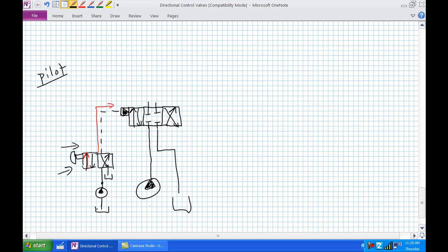Super pump is over here. Baby pump is right here. So basically, baby pump is just providing the tiny amount of pressure to activate that directional control valve, whereas super pump can do incredibly high pressure, incredibly high flow rates. So you might see a combination there where there's a tiny pilot pressure controlling incredibly large pressure in the system.